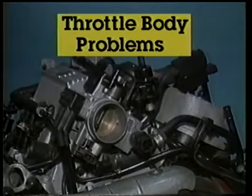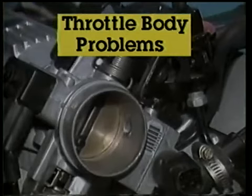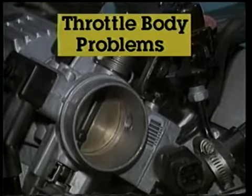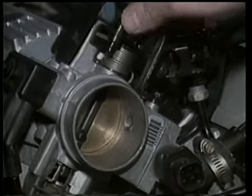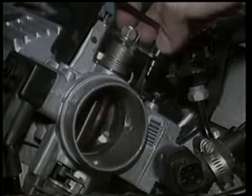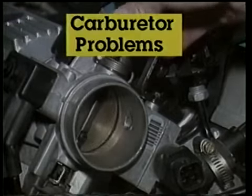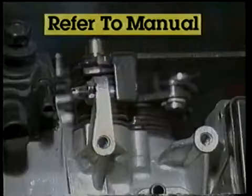Throttle body problems can sometimes develop after prolonged service. Throttle body service is needed when surfaces warp, if the throttle shaft wears, or if a gasket fails and begins to leak. A throttle body can have some of the same types of trouble found on carburetors because of their similar construction and operation.